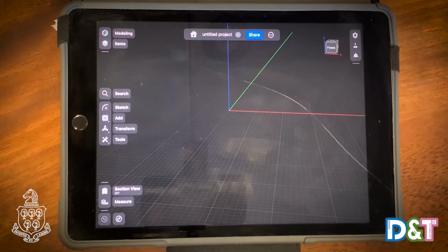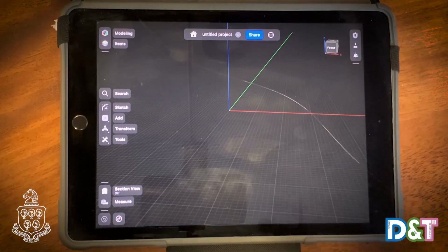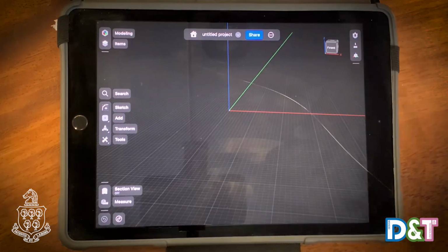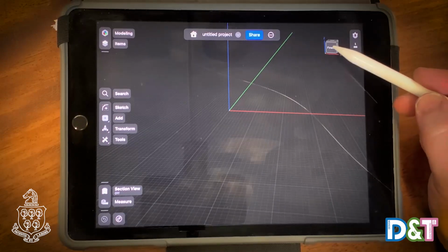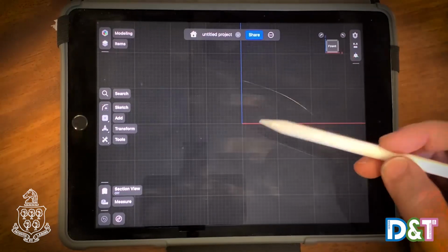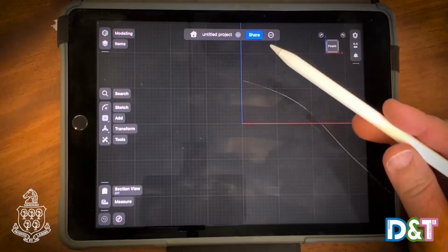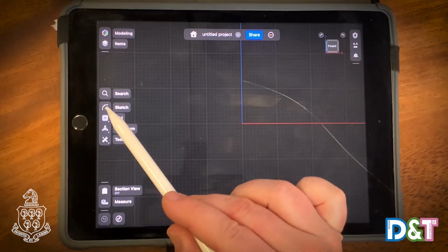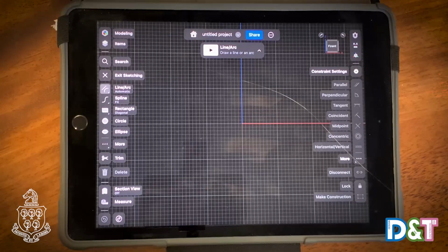So first things first with this pizza cutter, we're going to design, well not necessarily design because there's the engineering drawing, but we're going to draw up the handle part first, okay? So first things first, we're going to go to the front view, and I normally start designing directly where the 2 axes meet, just to make it a nice central point. And then we're going to click over onto the sketch button. And for this, we're going to draw the end of the handle, which is nearest basically the cutter.